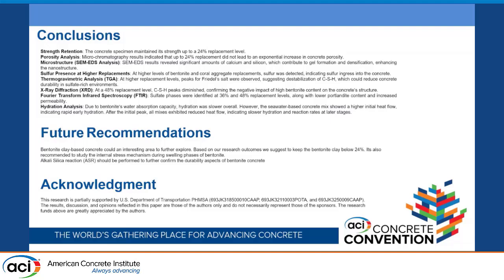For future recommendations, as bentonite clay based research is limited, and I didn't find many research papers in this area, we suggest that if someone is interested, then 24% should be considered as the upper level for cement replacement. We should perform more tests to understand the stress mechanism that is generated during the expansion process, and some durability tests such as ASR should be performed to further confirm the durability aspects of the bentonite clay.